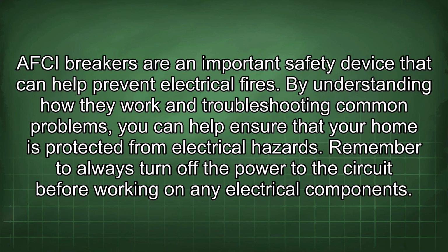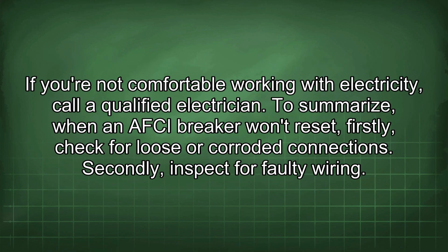AFCI breakers are an important safety device that can help prevent electrical fires. By understanding how they work and troubleshooting common problems, you can help ensure that your home is protected from electrical hazards. Remember to always turn off the power to the circuit before working on any electrical components. If you're not comfortable working with electricity, call a qualified electrician.